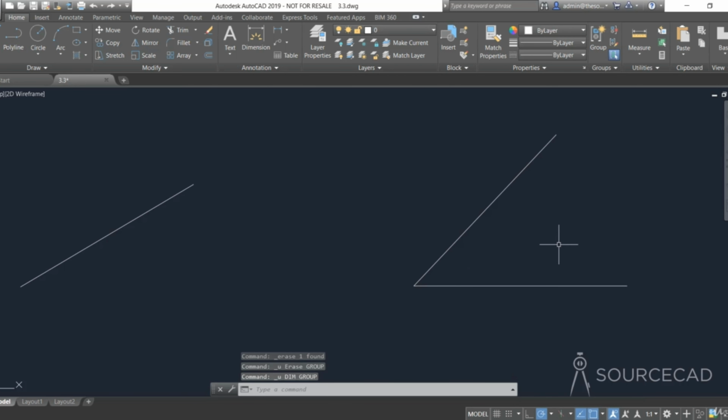So that's the whole thing about the rotate command. Rotate command will always rotate your drawing with respect to its original position. In this case, this was at 16, so it made a final angle of 30 degrees with respect to this line. If you measure it with respect to this, then you'll get 30 degrees. So I'm going to do that next. I'll go to rotate again, and I'll once again select this line and enter.